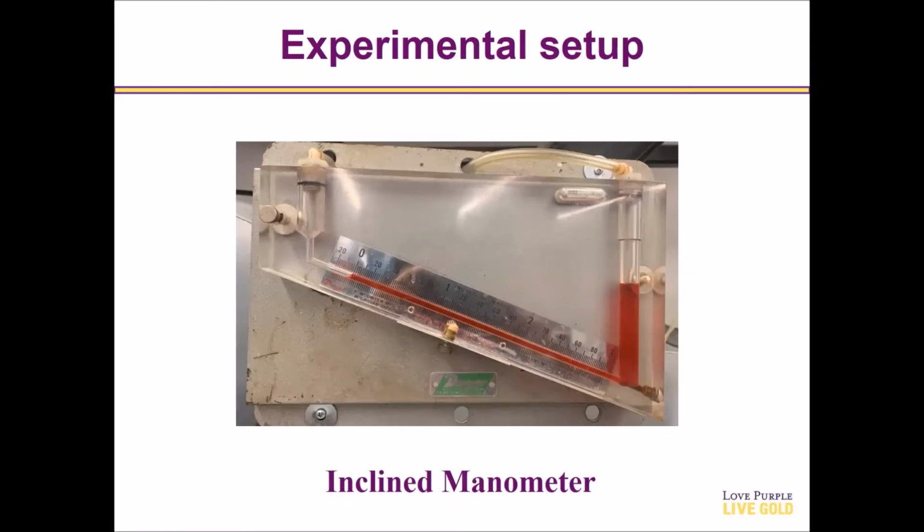The pitot tube which we showed earlier is connected to an inclined manometer. The kinetic head is converted to pressure head and it is measured as the oil level in the inclined manometer. However, the manometer fluid is red oil, whereas the scale is calibrated in inches of water. So you would be using the water properties for calculating the airspeed.